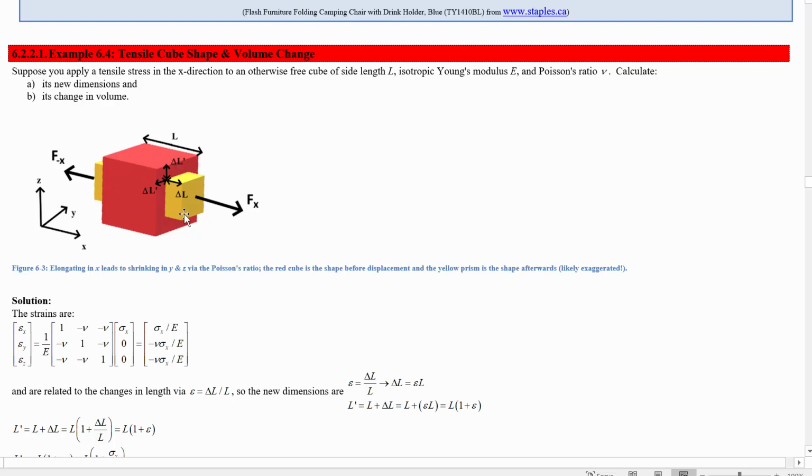But for a water balloon or rubber or something with a high Poisson's ratio, it'll compress in those dimensions to allow that extension to happen. You can think of it like the internal molecules don't want to be pulled apart, but they don't care about the shape and the organization of them. Whereas for cork, the molecules can be pulled apart quite easily, and it's like the 3 dimensions are totally independent.